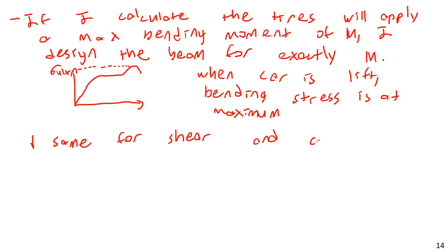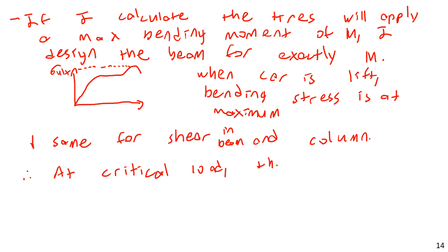Same for shear in the beam and the column. In other words, I assume I'm going to take everything up to the maximum. In other words, therefore, at the critical case, the big heavy truck, my estimated maximum load, my maximum truck size for this lift, at the critical load, the members are fully loaded at really their ultimate load.